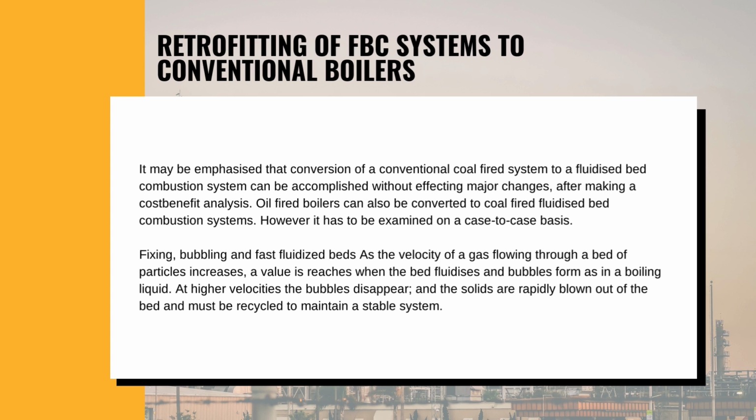Fixed or bubbling and fast fluidized beds. As the velocity of a gas flowing through a bed of particles increases, a value is reached when the bed fluidizes and bubbles form as in a boiling liquid. At higher velocities, the bubbles disappear and the solids are rapidly blown out of the bed and must be recycled to maintain a stable system.